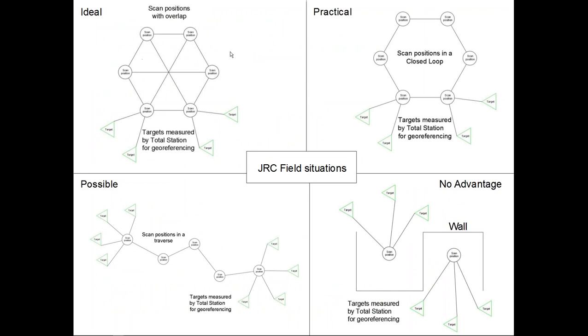And they, let's say like through magic, find themselves automatically where they are located and give a good result. Of course, you might still use targets in order to georeference. That's what the small green triangles are in this situation. As you can see, I just placed 4; 3 are enough, but 4 is, let's say, a minimum just to be certain that everything is going okay.